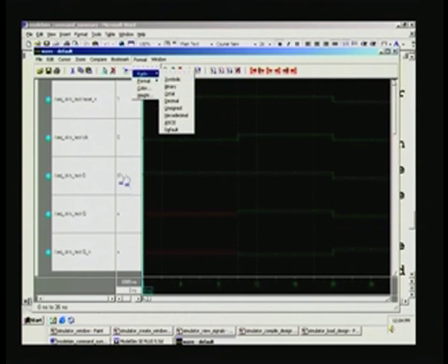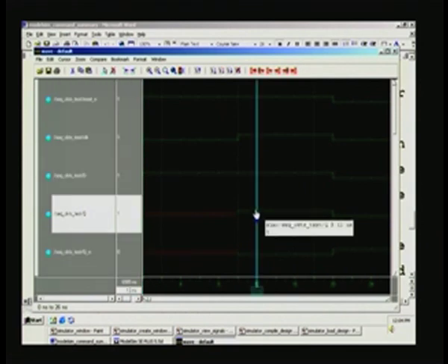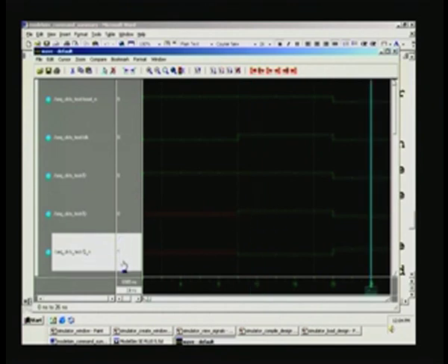So, let us say here we want all these signals which are already marked to be in binary. So, we just click on format, radix, binary. You can see that ST disappeared here in these two cases. Now, suppose I click the cursor here, whatever is the actual state will be indicated here. This is actually 0. So, this Q underscore n is 0, Q is 1 here. At different points it will be different, it has gone to 1. In this fashion you can click the cursor at different points and get the actual data displayed here, as I mentioned before.